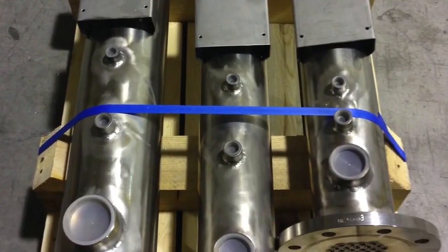If our refrigeration unit is always at 7 degrees, what we can achieve on the secondary side is typically 12 degrees. That is at least 5 degrees more. If we want to lower it, we risk having to put more exchangers in parallel and in series, so a lot of surface area to achieve the same performance, therefore to achieve the same temperatures. The average logarithmic factor is extremely important when we size the exchangers.